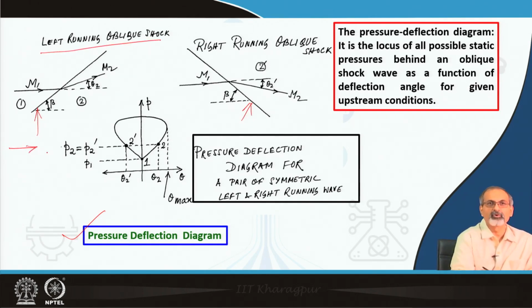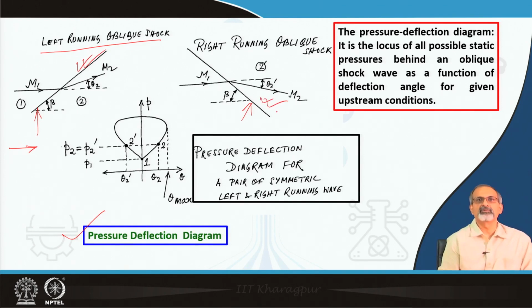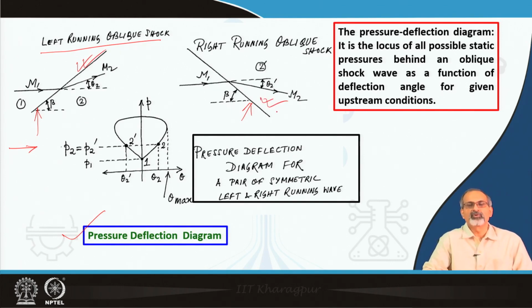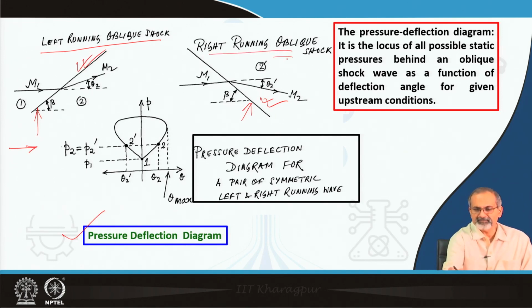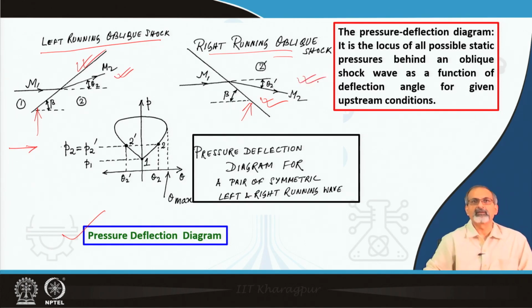The flow direction is from left towards right, and if you are pointing downstream, moving along with the flow, and you find this wave to your left, you would find a wave like this to your right, moving away towards the right if it emanates from your location, and thereby the names they attain. Because of the inclination they have to the flow, the flow across the left running wave would tilt upwards, while the one across the right running wave will tilt downwards.